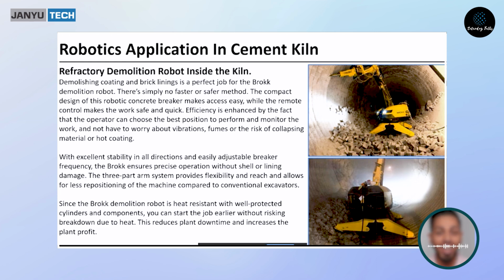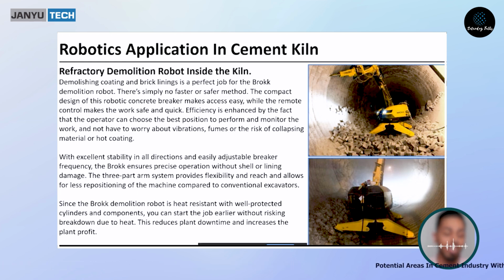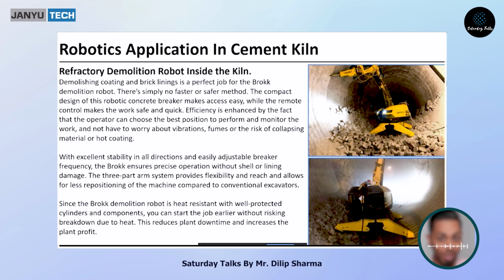Then the second issue is boiling inside the kiln. Boiling is also a phenomenon associated with raw material trace elements, properties, alkalis and chlorides and all that. This is also a very frequent thing, and when it happens, it chokes the cooler discharge, and then you have no option but to stop, brake, and then start. So these are also hazardous jobs.